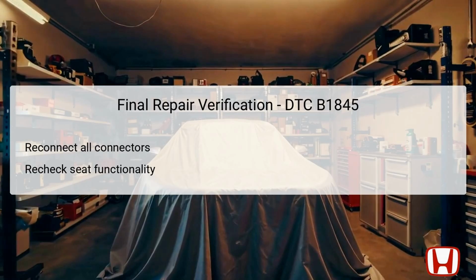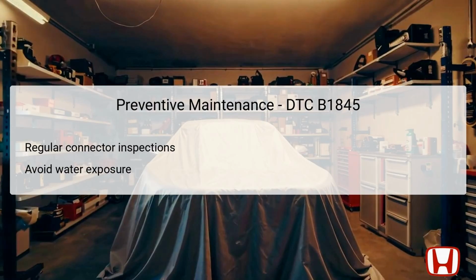Preventive maintenance is key to avoiding recurrence of DTC B1845 and other similar issues in the future. One of the simplest and most effective maintenance practices is to perform regular inspections of the connectors and wiring associated with the power seat system. Checking for signs of wear, corrosion, or damage can help catch issues before they lead to any significant failures.